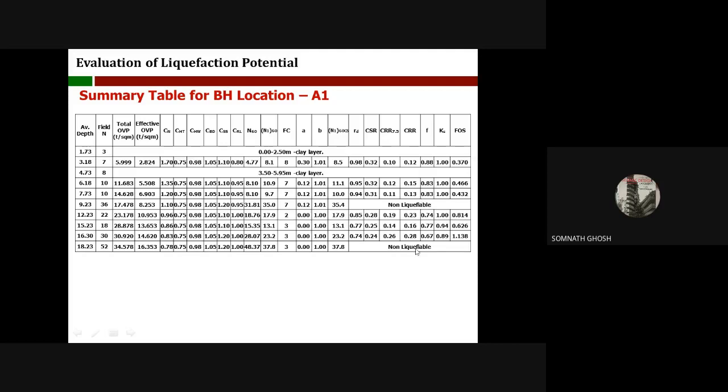These two layers are to be omitted. Naturally, the pile capacity will not be the same. It will be much less than that. So that is the problem. Now you can't do that. Now if you sign a drawing, even the geotechnical engineers have to write that all the soil properties, bearing capacity, skin friction, whatever it is, are obtained by considering the liquefaction effect.